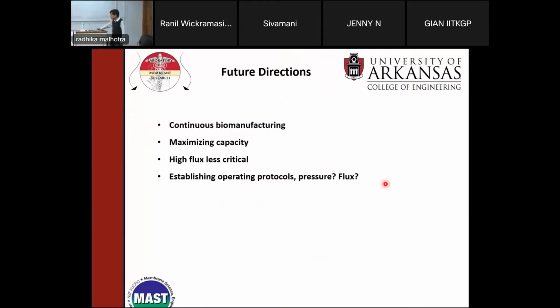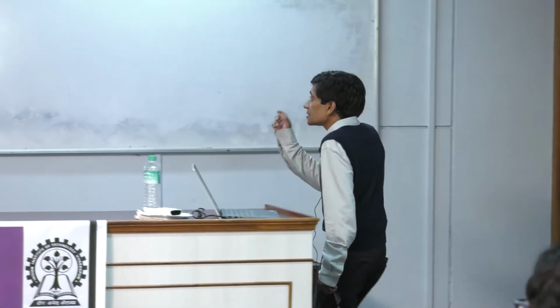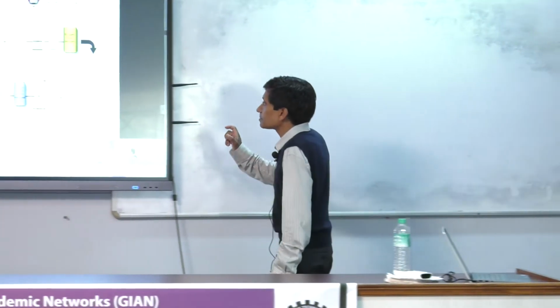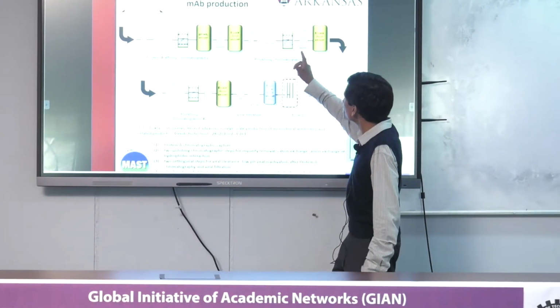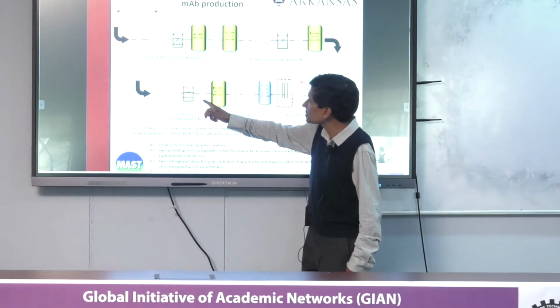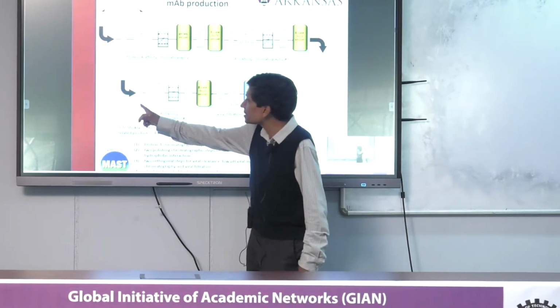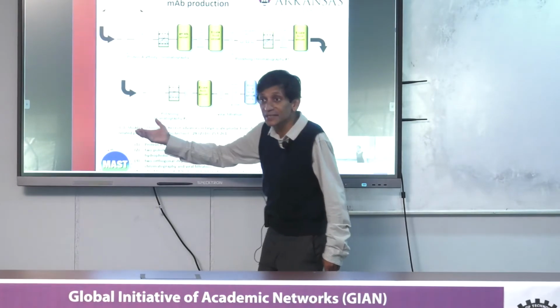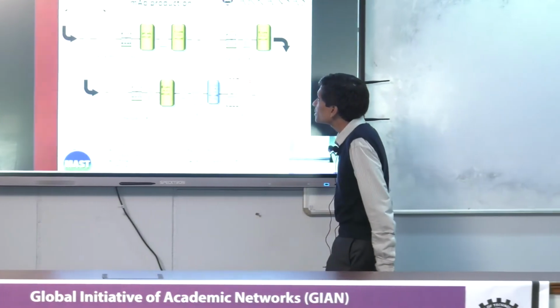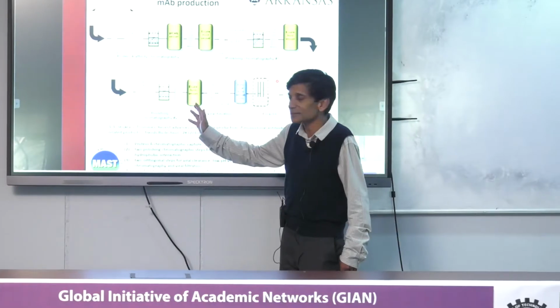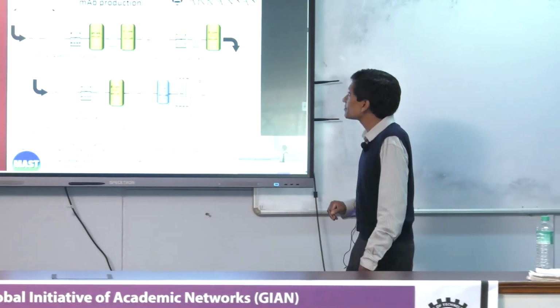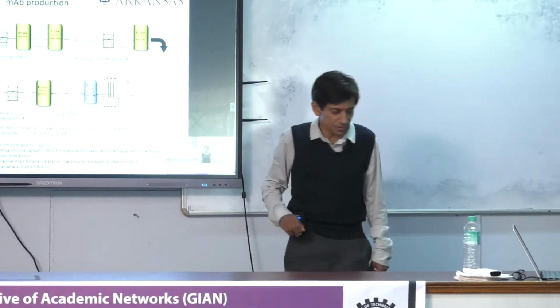And then I think that's almost the last slide. Yes. So if we look, this just highlights the downstream purification part. So I just want to highlight again. You have a sterile filter here, 0.2 micron. You have a sterile filter here. You have a sterile filter here. You have a guard column here, right, for your chromatography steps. That's typically a depth filter. So you can see how many membranes we use in all this. You have another sterile filter here at the very, very end, right? And you will have other sterile filters when you have buffers entering this system. So we have talked about a number of these different membranes that are used in the whole process here, okay?